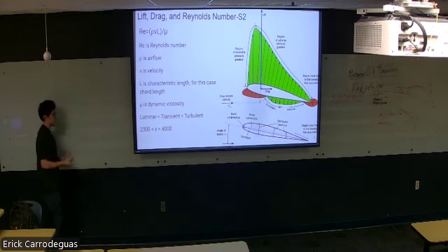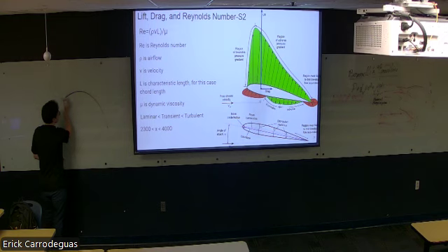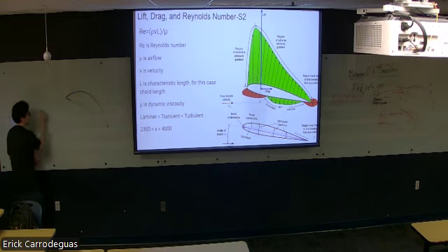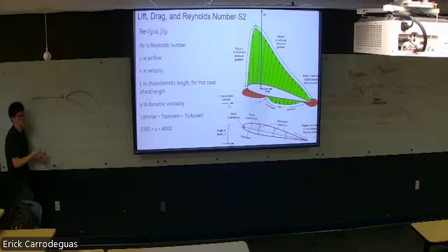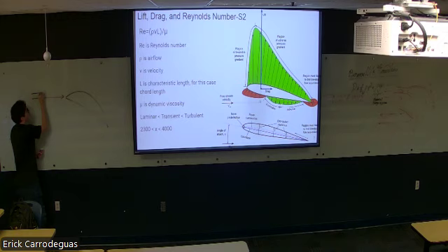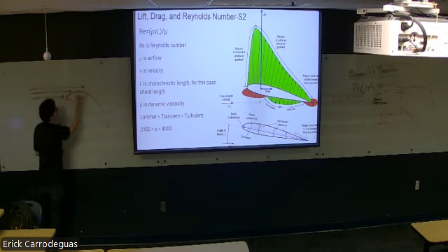When we're dealing with planes, and this is why we really need to use the wind tunnel correctly, you have an airfoil. You guys already understand that for there to be lift, air has to travel on top of this top surface. If air isn't on this top surface, then there's no lift. When you increase your angle of attack, less and less of the air flowing on top reaches the bottom of the trailing edge, right?